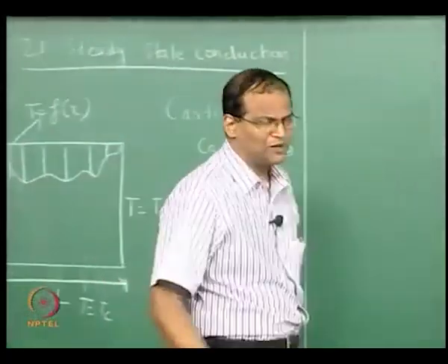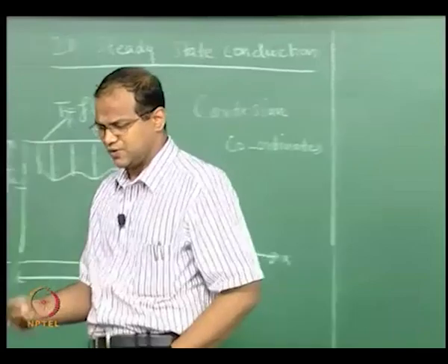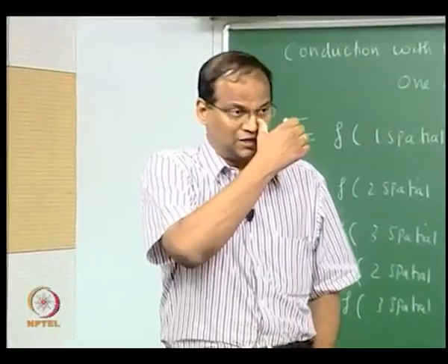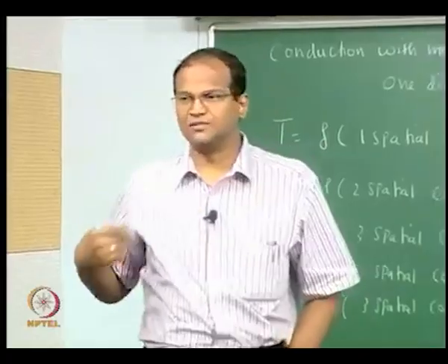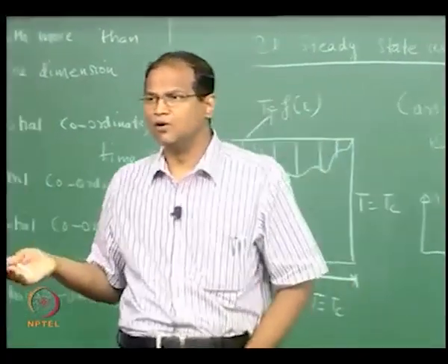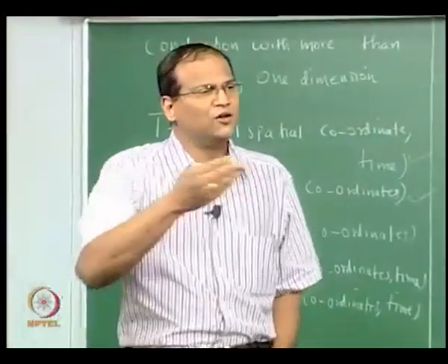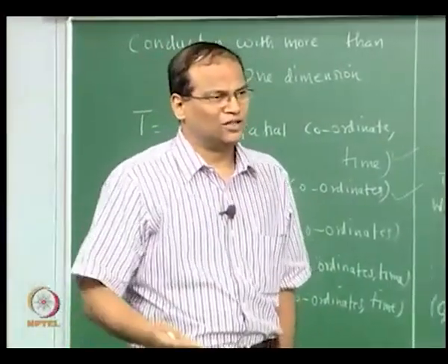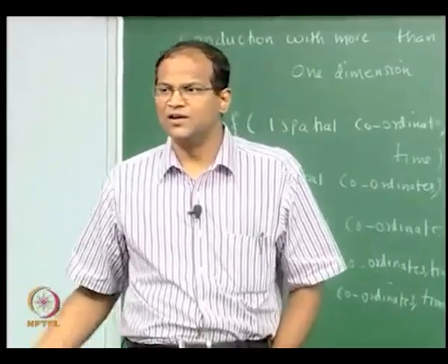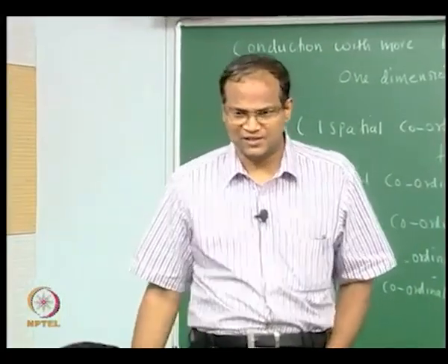So when do we get this two dimensional problem? When can we consider this two dimensional conduction? Basically if the slab is infinitely deep in the direction perpendicular to the plane of the paper, and it is bathed on three sides by a very cold fluid with a high heat transfer coefficient, you can assume that the three sides take on the temperature of the surrounding, take on the temperature of the fluid stream which is bathing this.